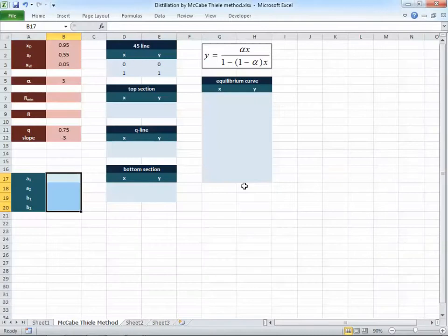Before I start with Excel, I just want to point out something really important. This is a program that you're going to make by yourself for your problem. Excel doesn't understand that this is distillation, or any concentrations, compositions, stages or equilibrium. It doesn't understand anything. So it's not like any simulation software. It won't give you an error message or pop up any problem with your calculations or input. It will just show you whatever you put, either right or wrong. So you need to be cautious because there might be something wrong and you wouldn't notice it.